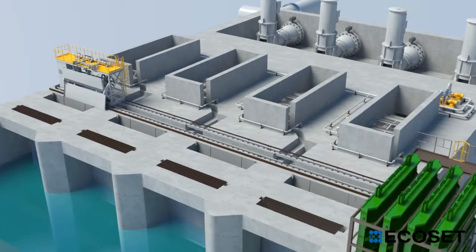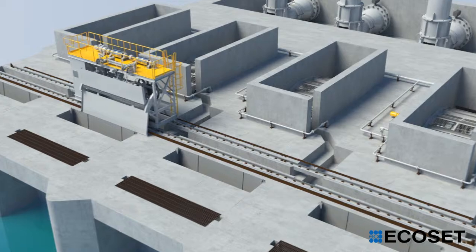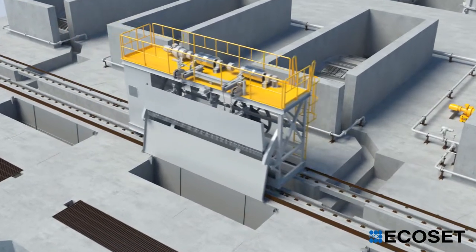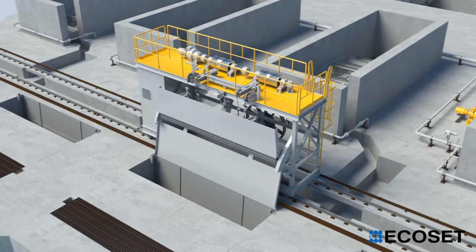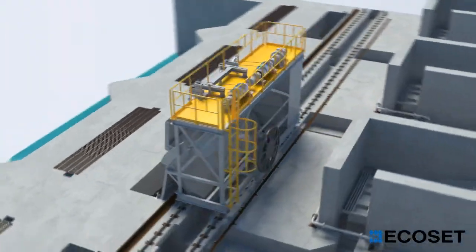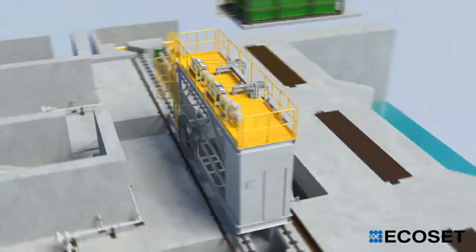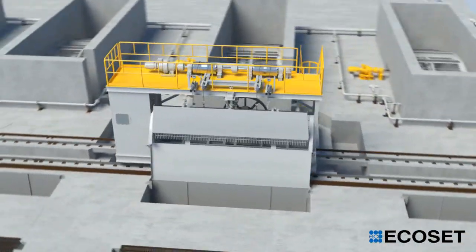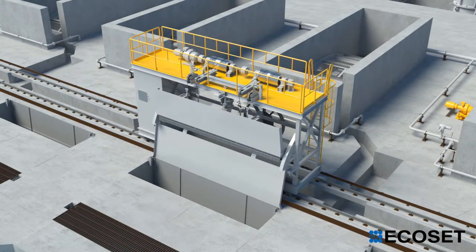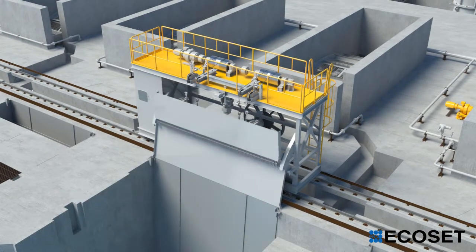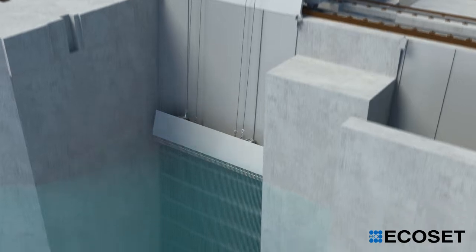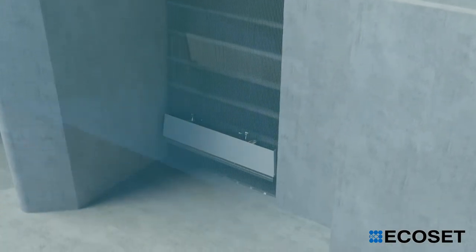The operating method of trash rake is based on on-site operation, and trash rake is operated by a local control panel. The operating mode of trash rake is one cycle operation, and one cycle operation consists of 4 operating steps. First, with the start command, the rake is lowered down the upstream face of the bar screen with the teeth open until it reaches the channel bottom.